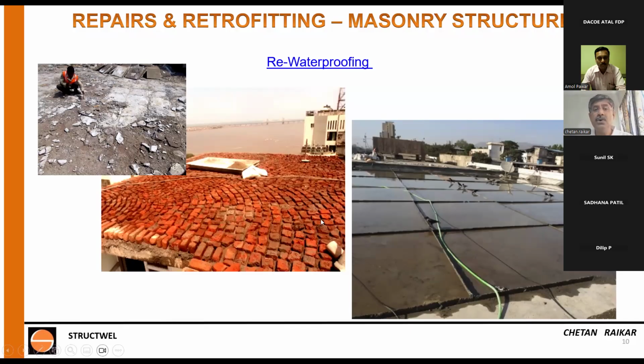Do you see that most of the joints in this brickwork are very uniform and narrow? These joints are about ½ inch to 1 inch thickness. A bad quality waterproofing has joints of uneven thickness, even 1.5 inches, 2 inches thickness. See, in olden days, they used to use brick bat, the broken brick pieces. But it is good to use even good quality full bricks. I would recommend personally to use good quality, full bricks in waterproofing. Because brick bat is a horizontal brick masonry that you are creating. Why we are creating? Let's see it.